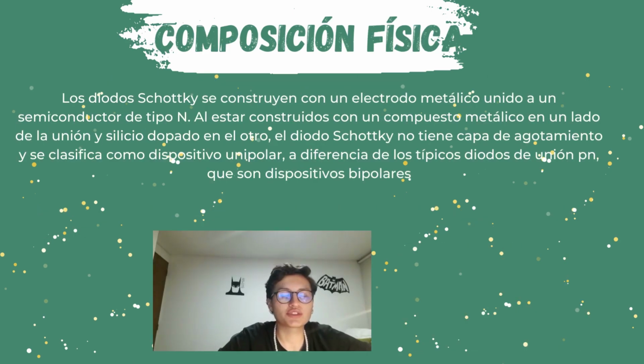Okay, the physical composition. Schottky diodes are constructed with a metal electrode attached to an N-type semiconductor, with a metal compound on one side of the junction and silicon on the other. The Schottky diode has no depletion layer and is classified as a unipolar device, unlike typical p-n junction diodes, which are bipolar devices.